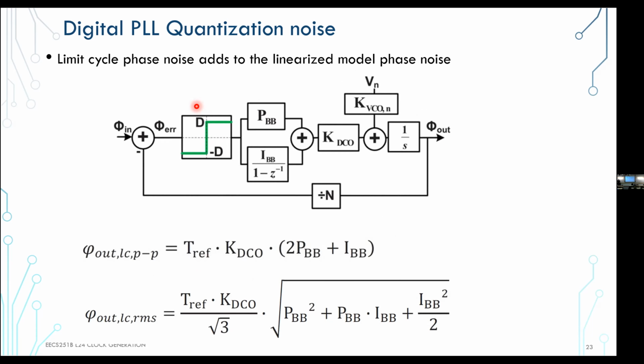It creates a limit cycle in the phase response of the PLL. Right? Another way people call this is bang-bang. So it either sets one target, and then the PLL tries to acquire that, or sets the other phase target, depending on where it's sampling here, because it's a very coarse sample, basically a 1-bit decision.